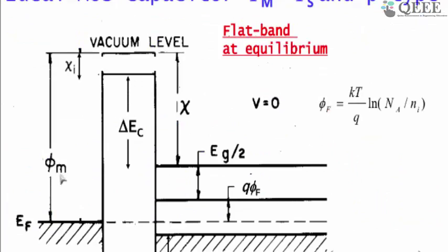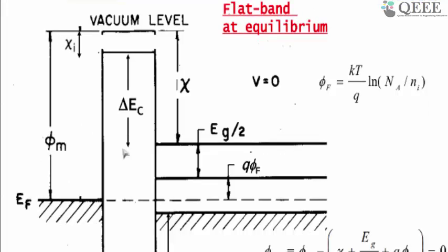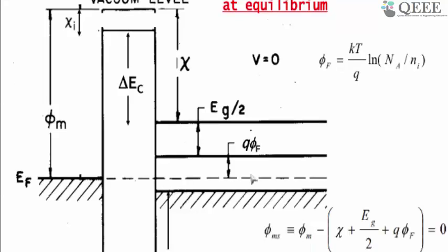This is the work function, from the Fermi level to the vacuum level. On the oxide side there is also no difference. Here is chi of silicon dioxide. But now when we change the substrate to p-type material, you see the Fermi level has moved towards the valence band edge. So now this is the valence band.